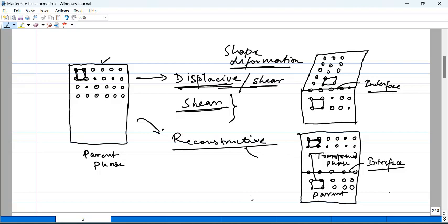Okay, so when it is cooled below Ms temperature, since it has to go to the martensite phase, the atoms have to move. And as I said, there are two ways the atoms can move. They can move by diffusion, by breaking the bonds, if it is allowed, if it is at a temperature where that can happen. If it is at a temperature where that cannot happen, then across the interface there will be slight movements to a new pattern, as you could see in this particular diagram.